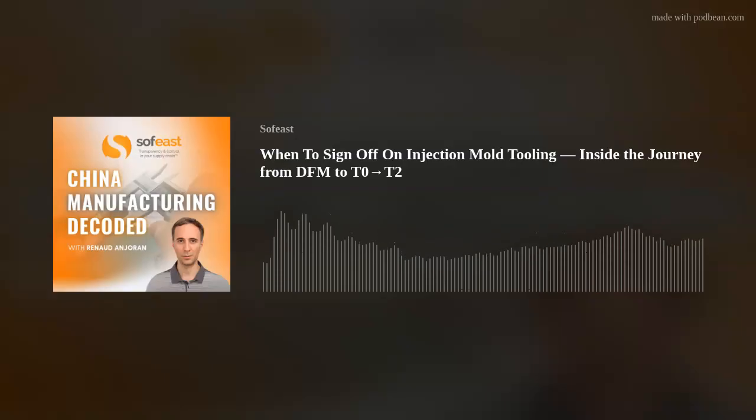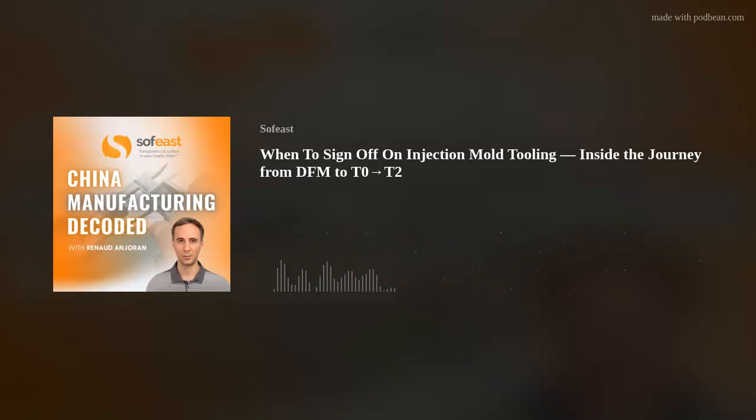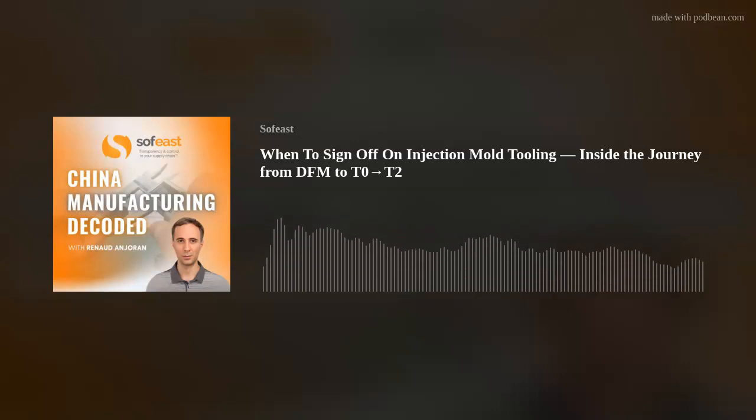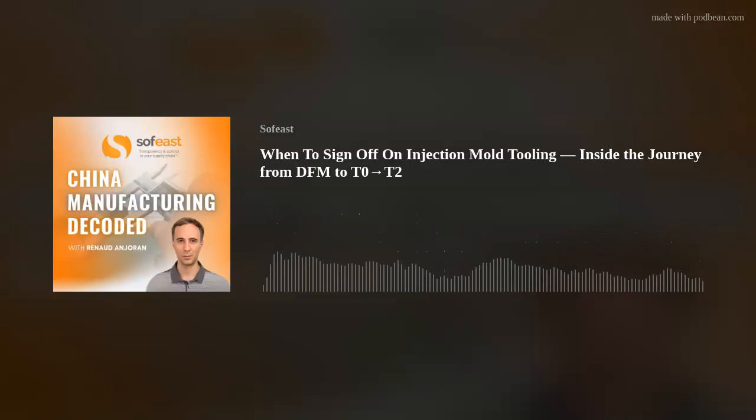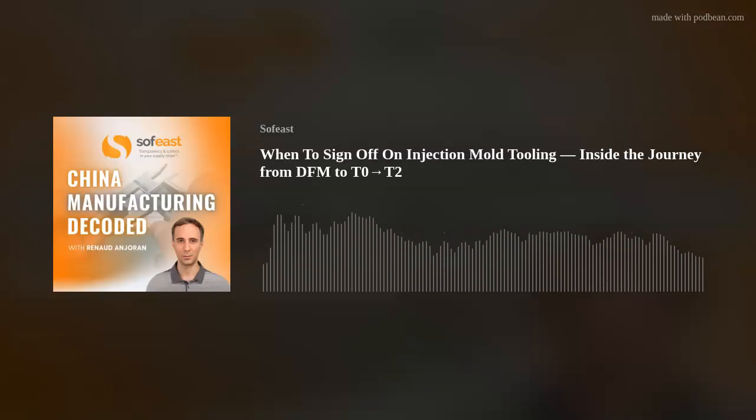Okay? So if you're not taking notice batch by batch, and please ask for the inspection reports each time you get a new batch of parts made from your injection molder, get the inspection report, because things do drift, things do change over time. And you've been running for a year or so and you've had a fantastic run and everything's gone absolutely swimmingly, and you're getting orders through the door and you've already done 500,000 shots. Well, please make sure you're still getting consistency, because these tools don't last forever.